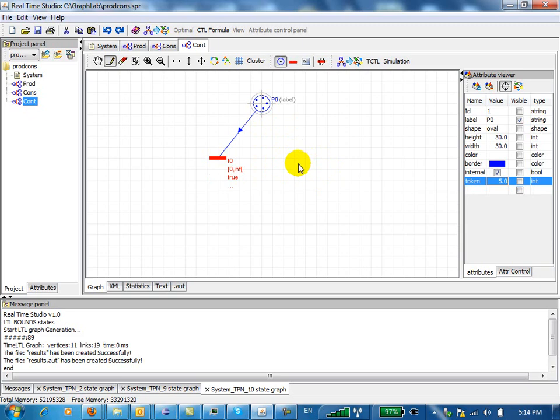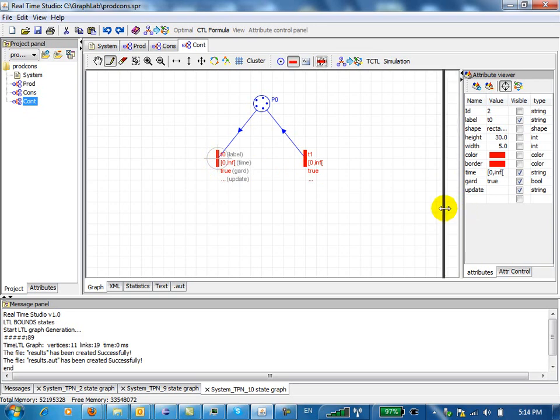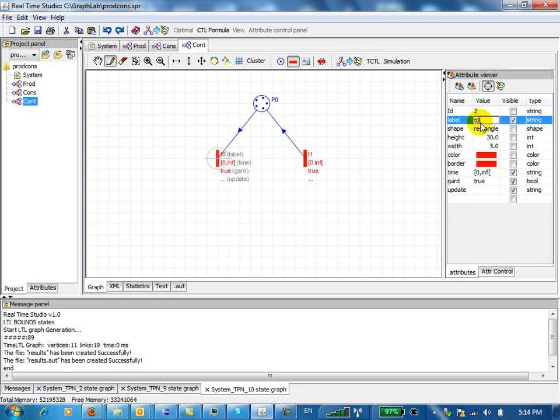And we're going to have another transition which corresponds to the consumption. So I will need another transition. I start from transition, press here, that's it. If I want to flip these transitions I can do it, by selecting the transition. So this transition is going to be called production. I would call it just P to make it easy, or PR, production. And this transition is going to be called consumption. C is consumption, or CO, consumption.